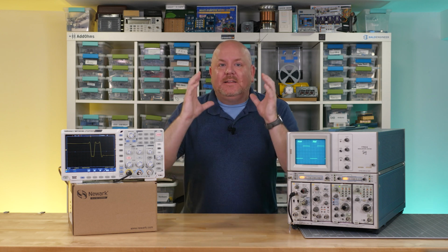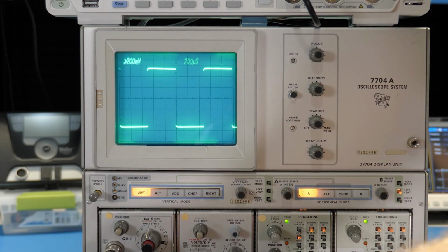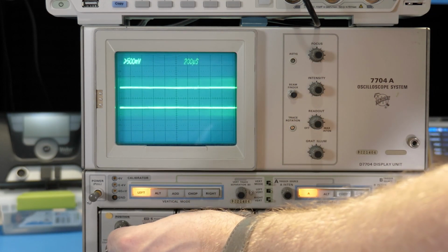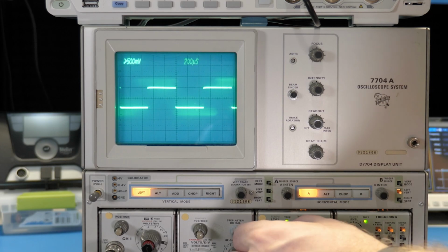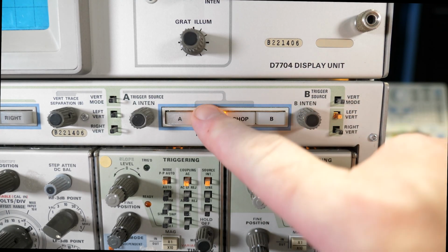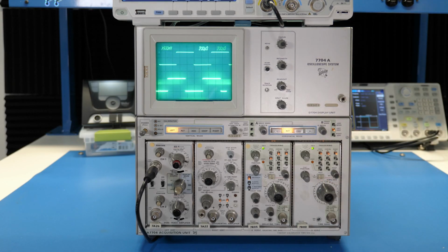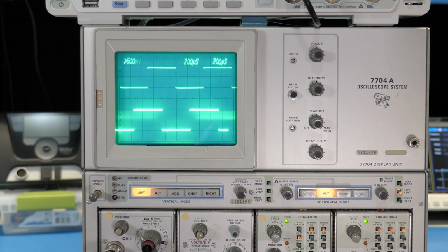What I want to do is get that same zoom display on the analog scope. So I went back to 200 microseconds per division and changed the volts per division for the next step. Since we have two time bases, we can put the horizontal mode into Alt, which causes the electron beam to sweep between the A and B time base modules. But because of persistence of vision, we see both waveforms as the scope switches between them. By the way, the intensity difference is because there are separate knobs for each trace, and I forgot to set them to be the same here.